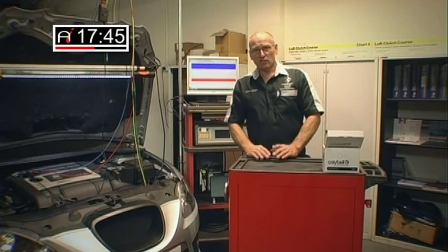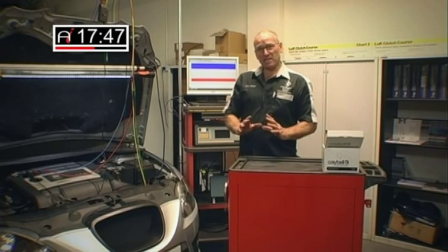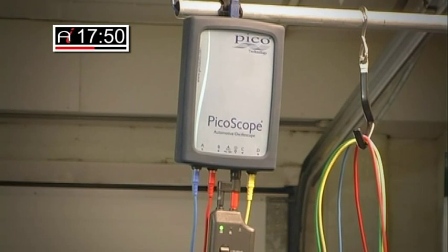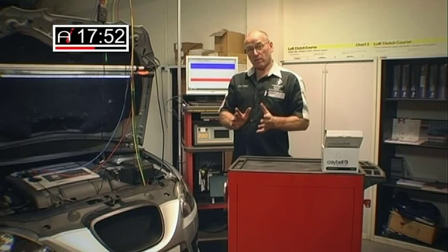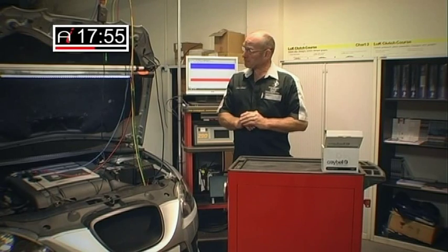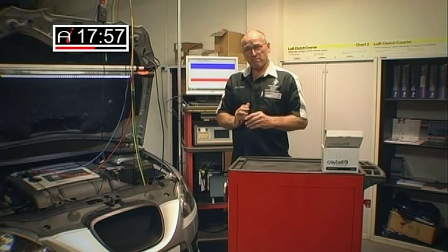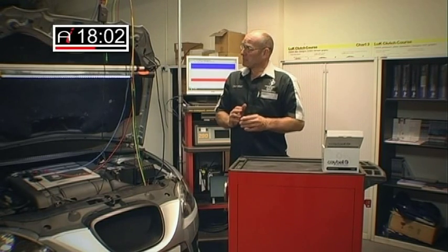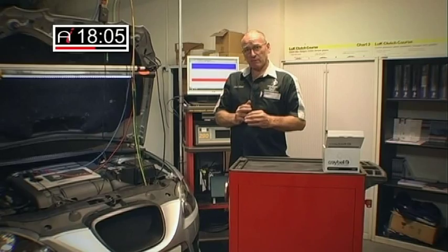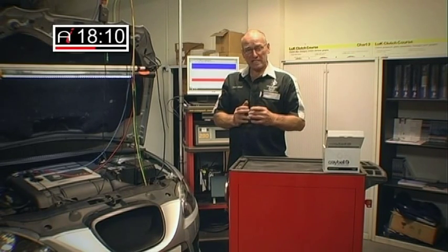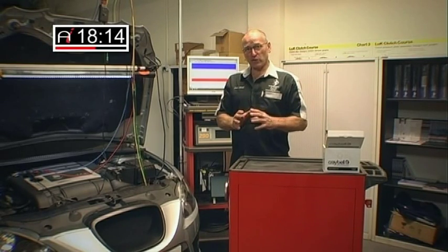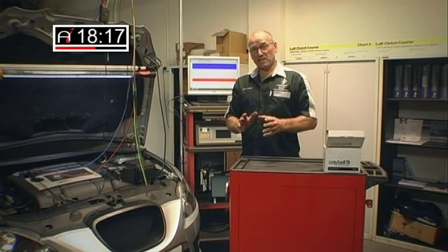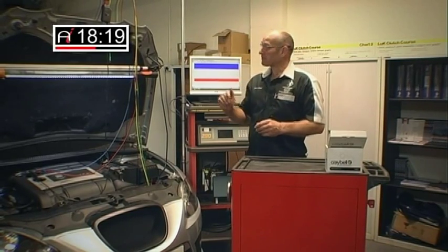Welcome back. During the short break, I've set up the oscilloscope with three options for looking at a digital air mass meter. One is to measure the frequency, and I have made the point you can use a multimeter for this. Secondly, to look at the conversion of that frequency to an analog display, and third, to look at current flow. So first of all I'd like to show you the connectivity and then discuss the setup options on the screen.